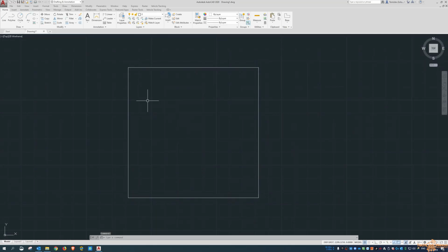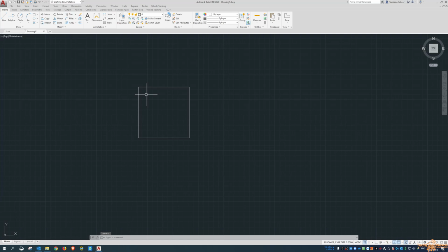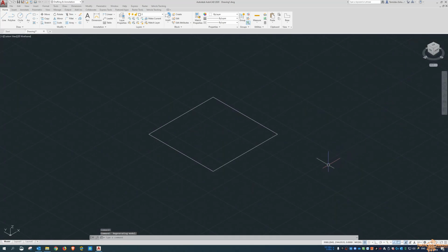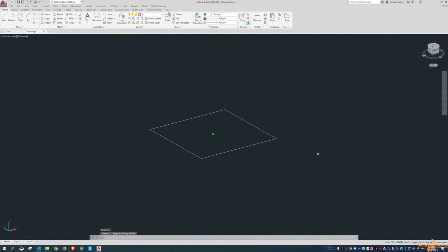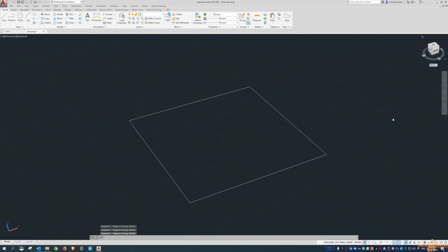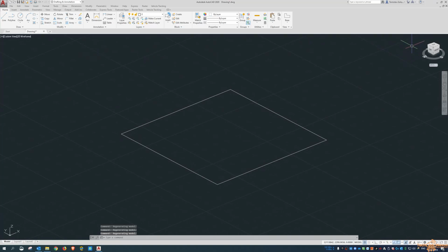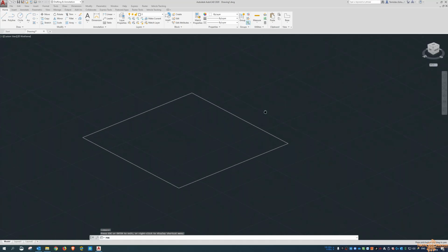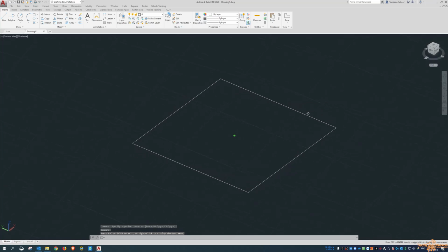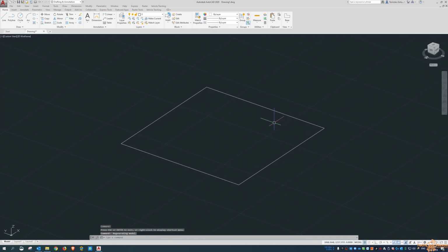Okay. Usually in an AutoCAD sense, you'll mix it up between 2D or 3D, depending on which way you want to look at it. If you want to switch to 3D, you can click on the home icon there. It rotates the view. You can press shift and your middle mouse button to rotate the view around, or you can click on the view cube to switch between left, front, right, all of that kind of stuff as well. If you switch to home, it'll take you back. To get the view cube, you can click on your view and click on the little minus sign at the top there, the viewport controls. You can turn the view cube on and off, and the navigation bar. The navigation bar is just a quick way to drag and navigate around your model. Otherwise, you can use shift and middle button to rotate, middle button to pan, all that kind of stuff.